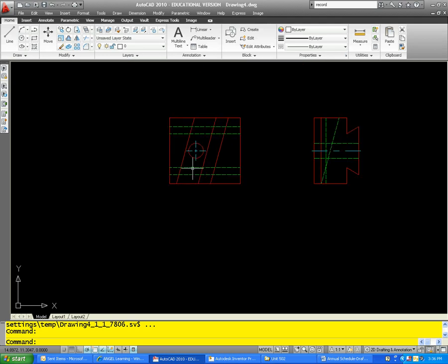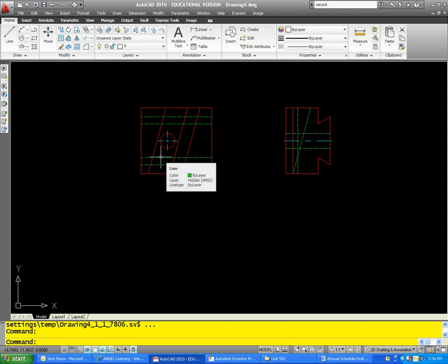Now when it says secondary auxiliary view, that means I'm going to be using the primary auxiliary view to develop the secondary auxiliary view. And regardless, had the directions said just draw an auxiliary view to show the true size of surface A, you would have to draw the primary auxiliary view showing the angle between planes A and B first. Okay,